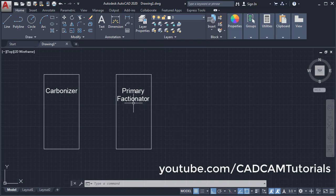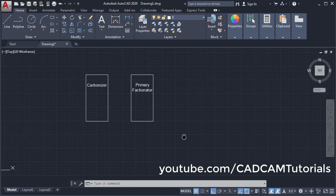And if you want to adjust the position, you can use the move command. Click on move. Select this text. Enter. Click base point and adjust the position and click. Then zoom minus.